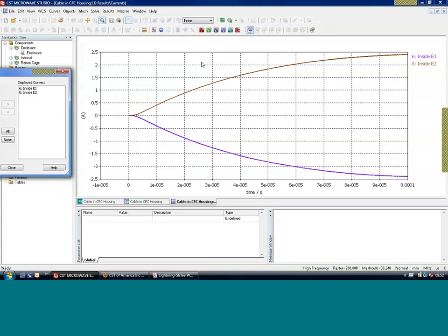And this, of course, is particularly important when we're thinking about modern aircraft, where the amount of composite material is increasing dramatically, so the coupling which we get through is obviously going to be a lot higher than we were getting with traditional metal fuselage aircraft. And what we can see here in the software is that we have the ability to look at these different material properties and understand how they impact the amount of current which is going to couple through and couple onto an internal cable.